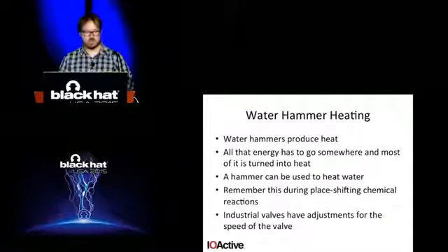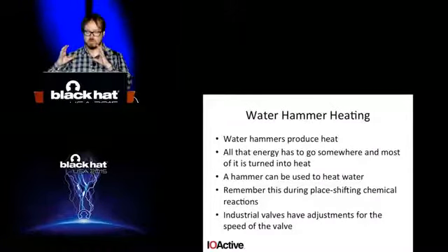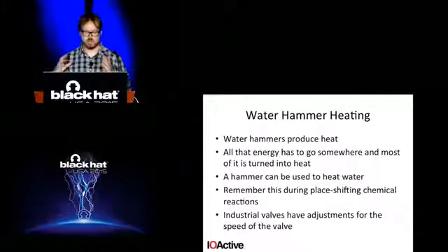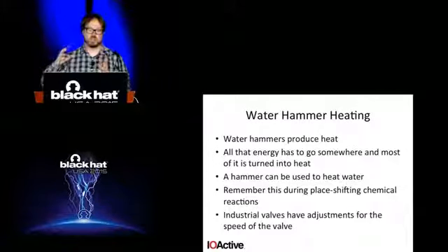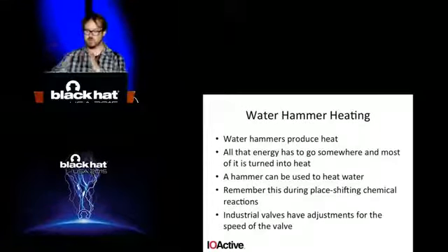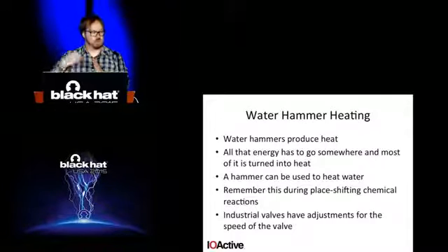So one of the things that you can get with water hammers is you have this big volume of water moving through the pipe, and it comes to a sudden stop. That's a lot of energy. The energy there is almost always converted to heat. So if you go look at where a water hammer has actually destroyed a piping structure inside of a factory, one of the things that's almost always observed is that the pipes are hot to the touch. So if you open the pipe and let the water slide through, and you slam it and the water slams to a halt, it's going to turn most of that energy into heat. And if you open it and close it again and it slams to a halt again, you get heat again.